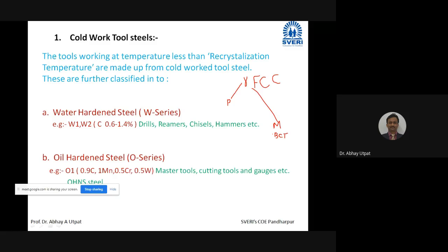You will hear a kind of hissing sound. What is that? It is a very fast cooling process. Because of this, there are chances of crack generation in your steel component. There is a probability that your part gets distorted. It will lose its shape and there may be cracking.